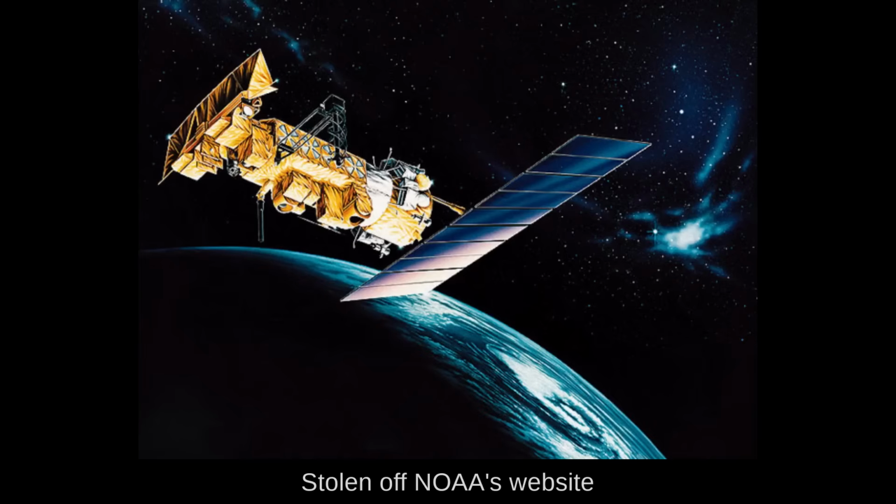With the software sorted, it's time to look at the radio. The NOAA polar orbiting satellites transmit on 137-ish MHz, and a bandwidth of about 50 kHz is recommended to deal with Doppler shift. This isn't much fancier than a regular FM radio, except it's 20 MHz higher up in frequency.